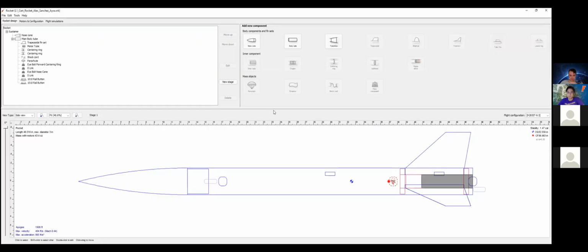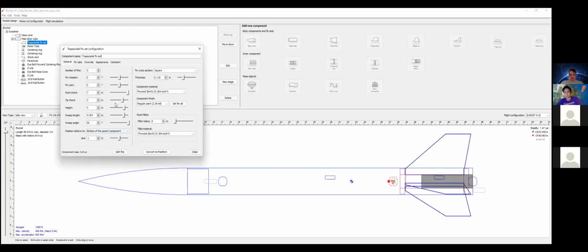And back here. Okay, so this is what a standard rocket might look like. Stability is 1.47, which is pretty good. It's more than enough for what you're going to need for an L1 flight. There's obviously fallacies because this is when I was a freshman and I didn't know what I was doing. So I kind of just designed it. You're free to play around with the design of the fin. Play around with the angle that it's at, how far back you want it swept, which also affects your stability massively.